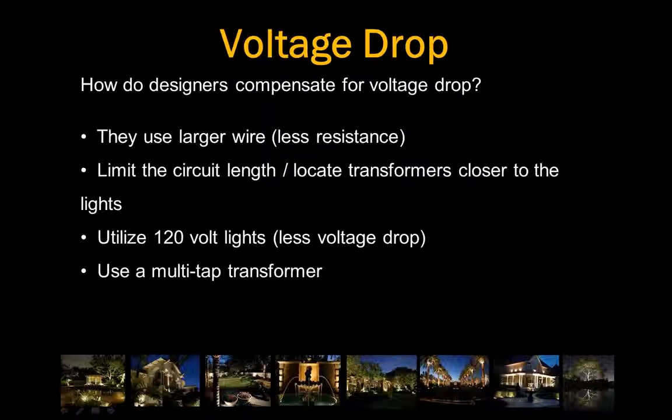We'll use a multi-tap transformer, but again, that doesn't really help for the voltage drop. At the end of the line, you'll get them all to turn on, but they won't be evenly lit. Lower the lamp load by using LED, which is not a bad thing. In fact, that previous example that I showed you with a voltage drop across the house there, if I were